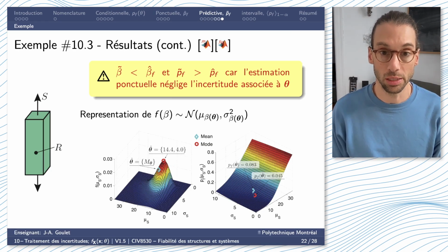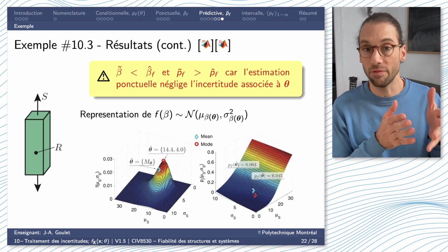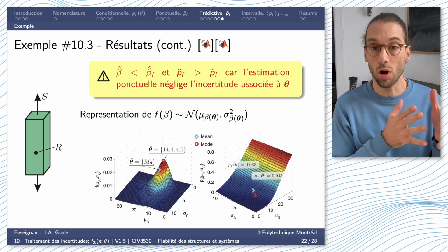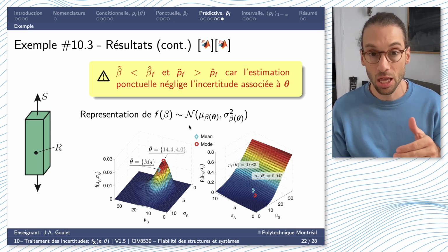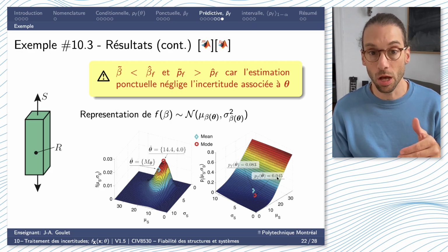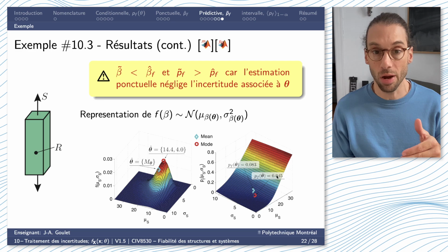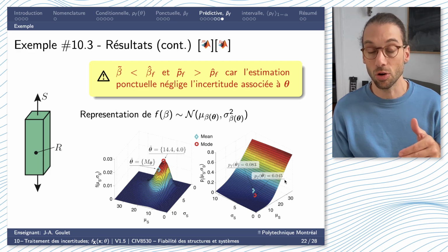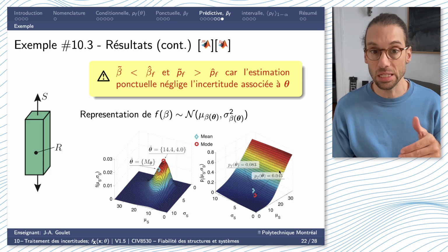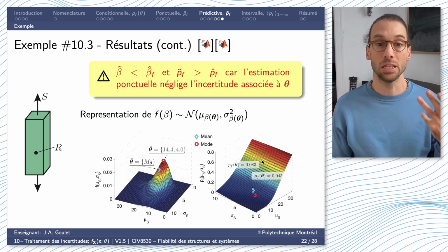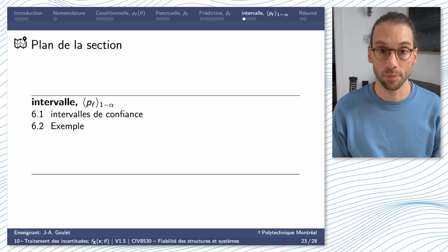that failure probability. And you can see we evaluated here that the probability of failure was around 0.11 for the predictive estimate, compared to the other two point estimates, where we go to 0.08 and 0.045. These are not conservative, okay? Because these neglect uncertainty. They're not safe estimates to be used.